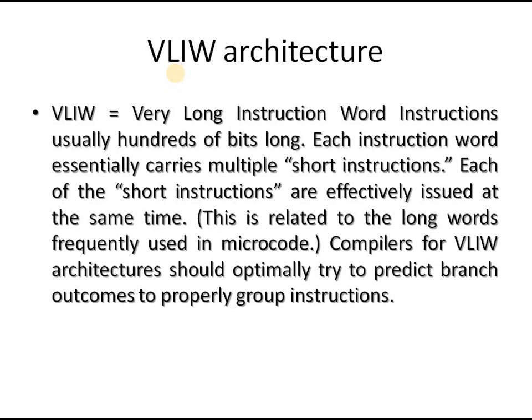Each instruction word essentially carries multiple short instructions. Each of the short instructions is effectively issued at the same time. This is related to the long word frequently used in microcode. A compiler for VLIW architecture should optimally try to predict branch outcomes to properly group instructions.